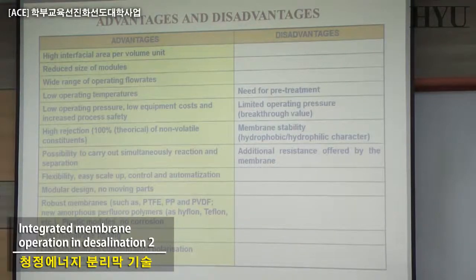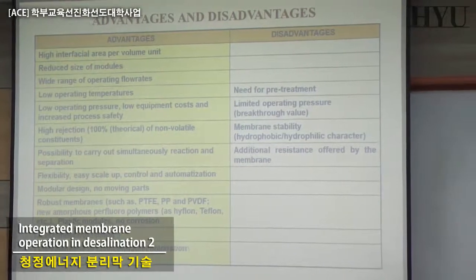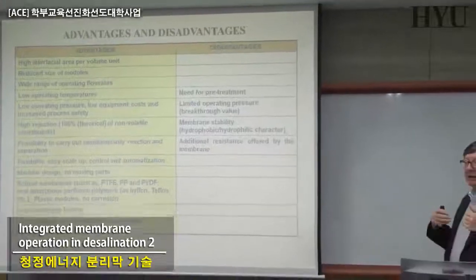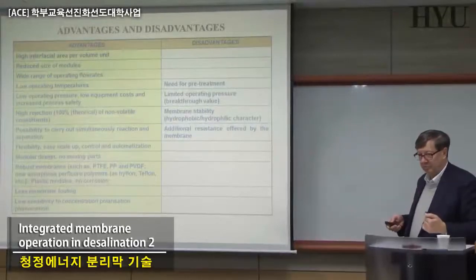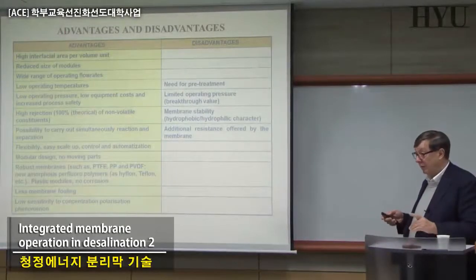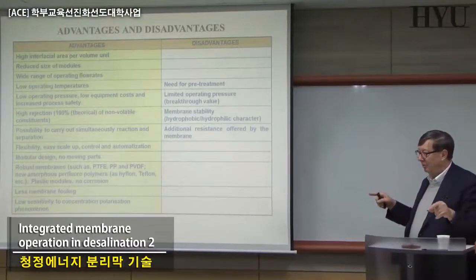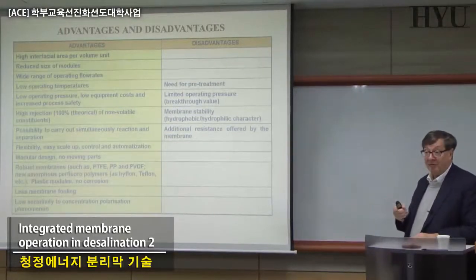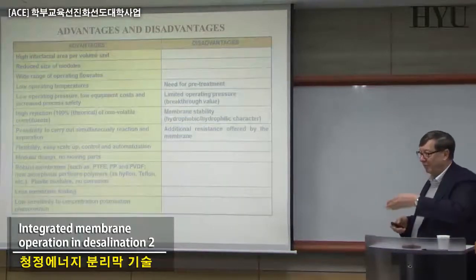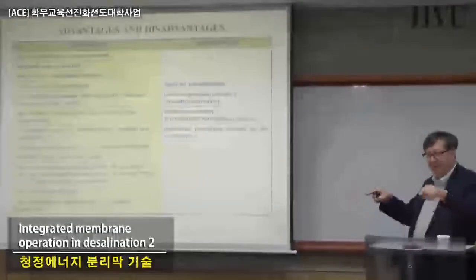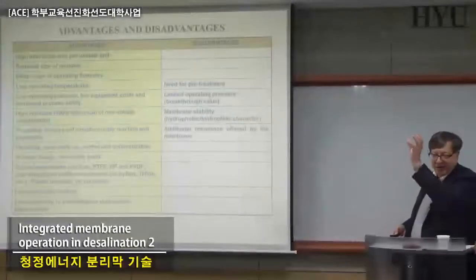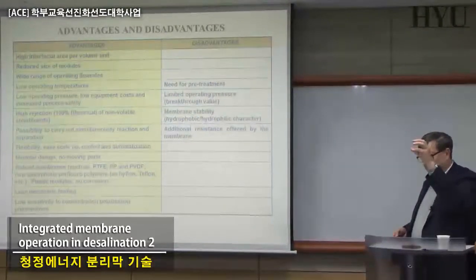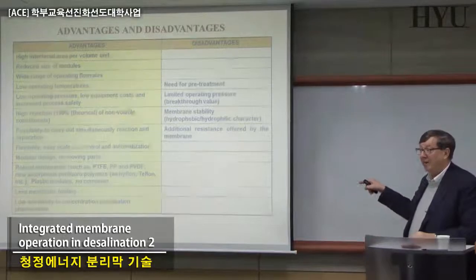Now, the liquid entry pressure is a function of the size of the pore. So in principle, we need membranes with uniform pore size distribution, in such a way that we can calculate the liquid entry pressure and work at a pressure lower than that one. But as you know, in all the traditional membranes you are preparing today using phase inversion, you never have a very sharp pore size distribution. You have a pore size distribution relatively wide in spectrum. When you say 0.2 microns, it's just the average. The highest number of pores is 0.2, but always you have pores that can be 2 microns, 5 microns.